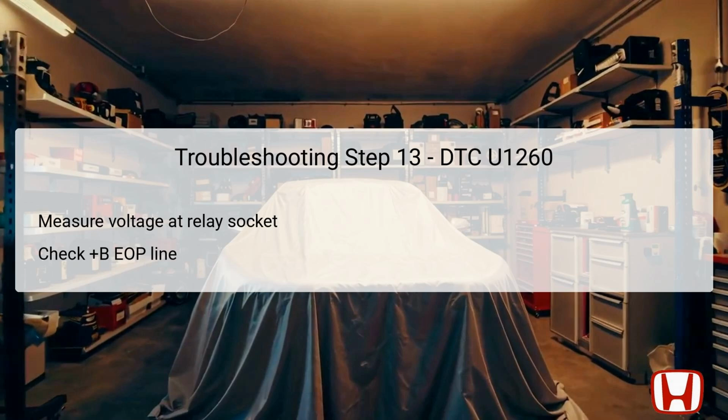If the technician detects battery voltage, it confirms that the wire is intact and capable of supplying power to the pump when required. Conversely, should no voltage be present, it points toward an open circuit that needs repair. This step serves as a pivotal moment in confirming the integrity of the power delivery to the auxiliary pump.